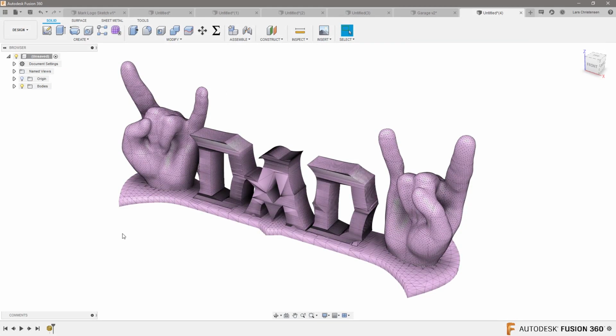If we don't need to make any changes to this, and I'm moving a little bit away from your question for just a second, Ryan, of course, you could just have printed that. You could have opened up your 3D print application to send to your printer and be done. But if we wanted to convert this into a solid, we didn't have to. So what Ryan did was he used an STL to IGES converter so you could get it converted. We don't have to do that unless holding that accuracy of 100,000 triangles is important.